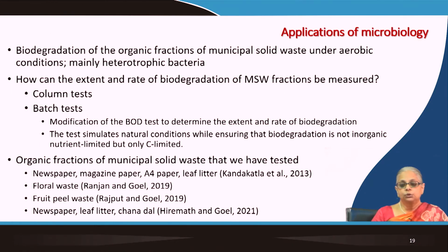Let us now come to the second part. So now we can take a look at another test. Using the same principles that are part of the BOD test, we've taken the same ideas and transferred them to an aerobic biodegradation test, measuring the biodegradable potential for different organic fractions of municipal solid waste under aerobic conditions.